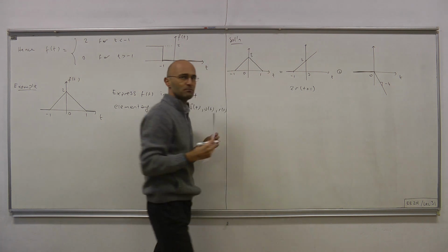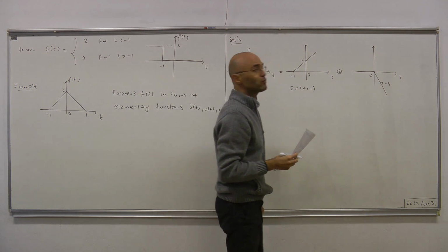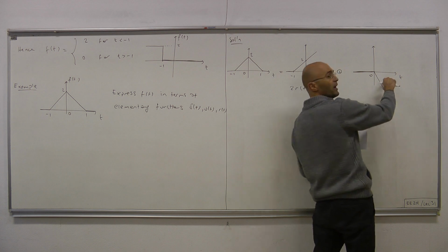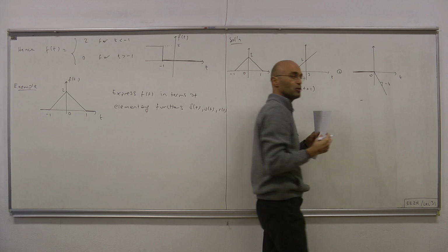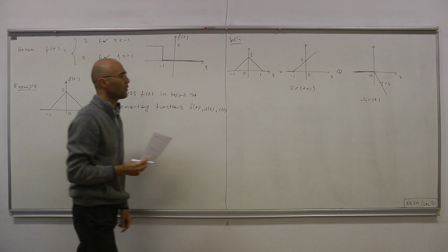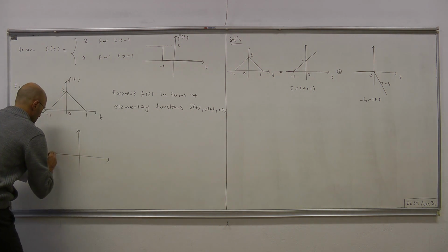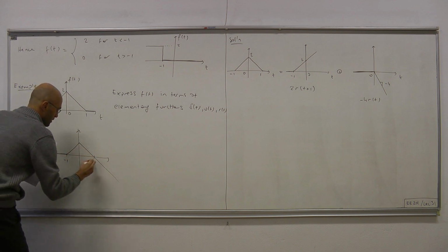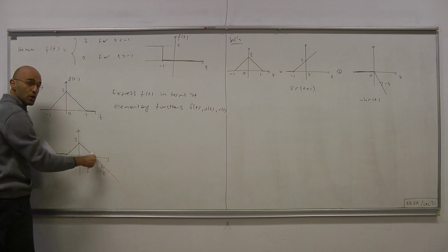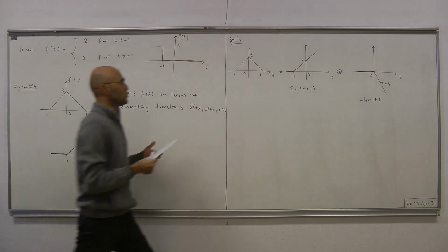But that slope of minus 2 becomes 0 at t equals 1 and remains 0 for future times. Therefore, to this we have to add yet another function so that the sum will give us f of t. By the way, this is the ramp, but it's upside down, therefore we have to put a minus sign before, and the magnitude of its slope is 4, therefore it's minus 4r(t). So far what we have is this plus that, which yields something like this. Minus 1, 1, this is 2. Now everything is fine until t equals 1, but here the slope is minus 2. From t equals 1 to the future, we want it to remain constant, 0 slope at the value 0. So the last thing that we should add should be